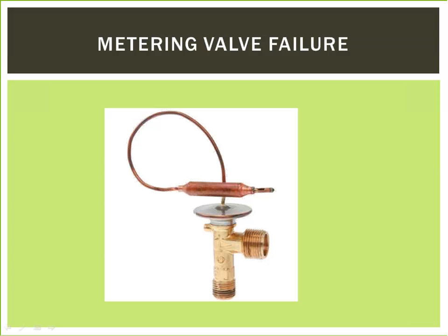If the metering valve fails, there will be no reduction in temperature to the evaporator and no cold air. If the valve fails in a completely shut position, it will create a restriction. Restrictions will result in the low side being excessively low, sometimes to the point of going into negative pressure or vacuum. Restrictions can also be created by system contamination.